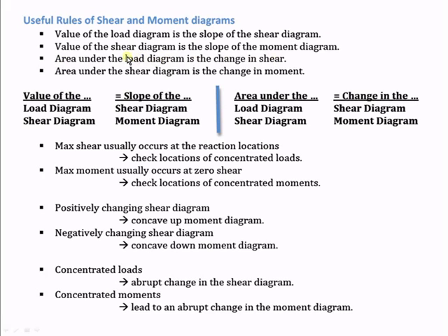Okay, because we can integrate the load diagram to get the shear. Integration is finding the area under a curve. So the area under a load diagram is the change in shear. And notice we have a similar thing said from shear to moment. Okay, so we're going to do the exact same process. So these are a bunch of different ways of saying the same thing.